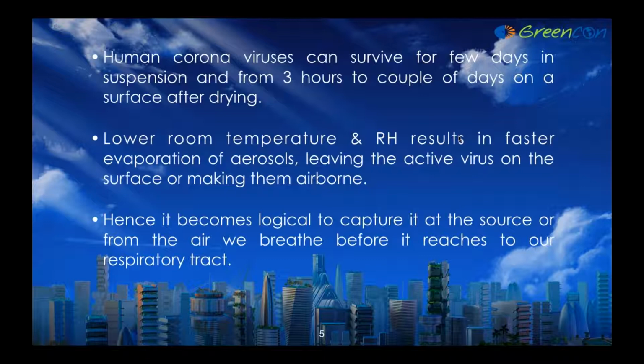We've been talking of various temperature and RH which is recommended, and the basic reason remains that at lower room temperature and lower RH, which is say below 50 or 40%, the evaporation happens faster and the aerosol which is containing COVID becomes airborne and makes life difficult. The basic fundamentals, we would go back to our kitchen exhaust ducts, and we know that if we have to handle any kind of particles that are generated in the air, it is better to capture it right at the source instead of allowing it to go into the entire space and then take it forward.